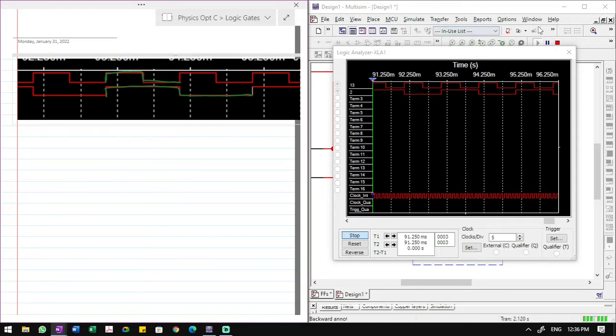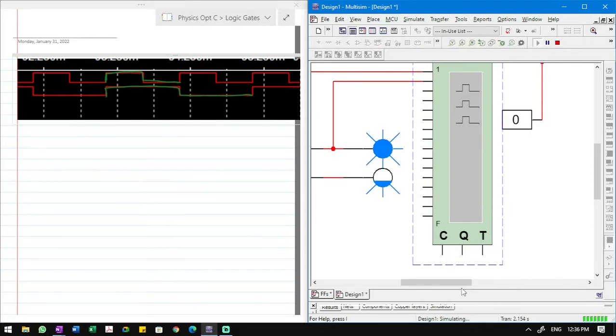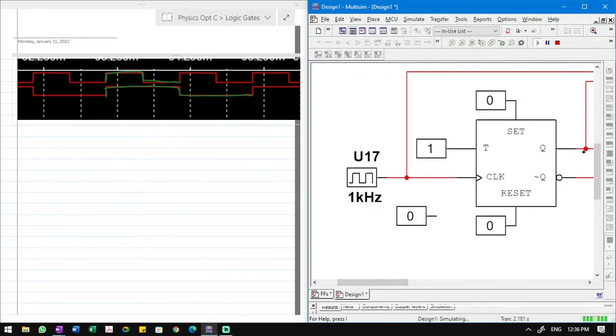So in this circuit here, if I were to remove the logic analyzer there, the output, and remember we only really focus on the output Q, okay? The frequency of the output Q in the toggle flip-flop is always half of the input frequency, right? Because according to this logic analyzer graph, the periodic time is double, right? So the primary application of the T flip-flop is what you call a frequency divider, right? It divides whatever input frequency you set, right?